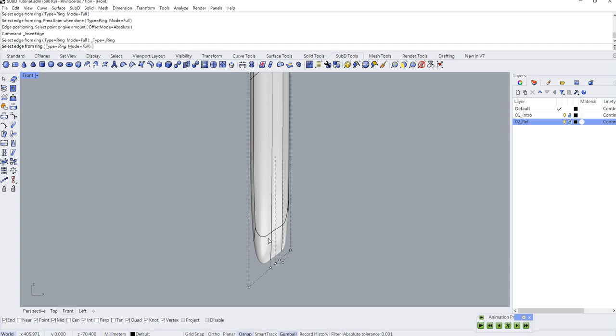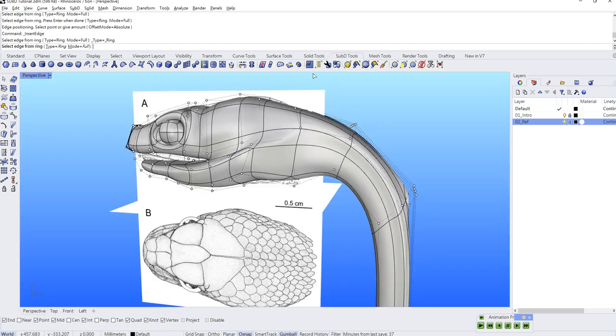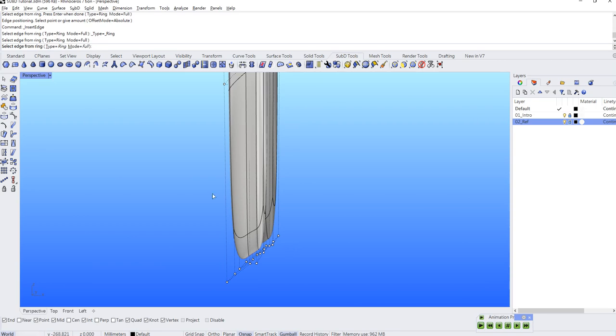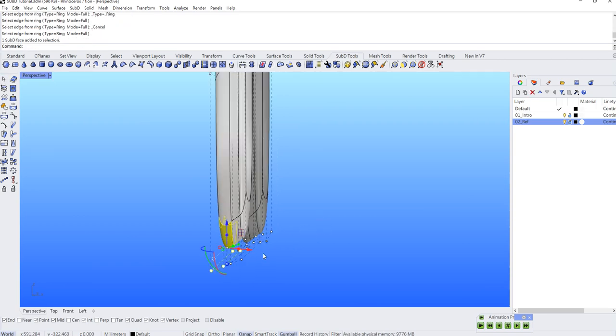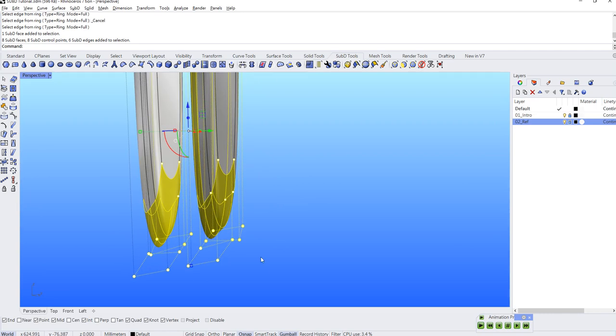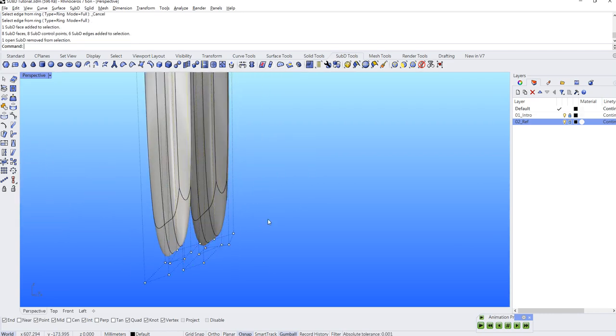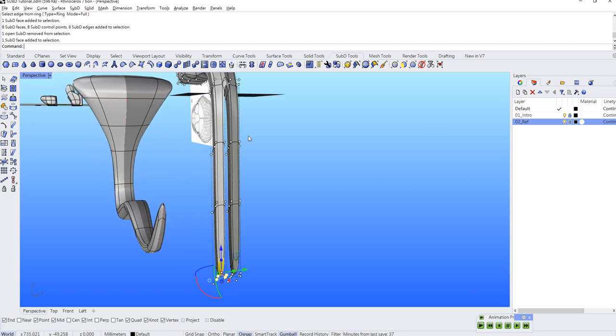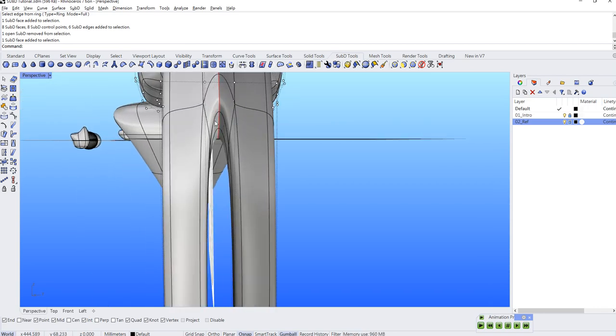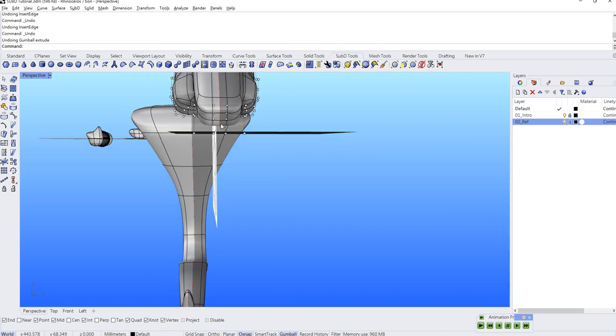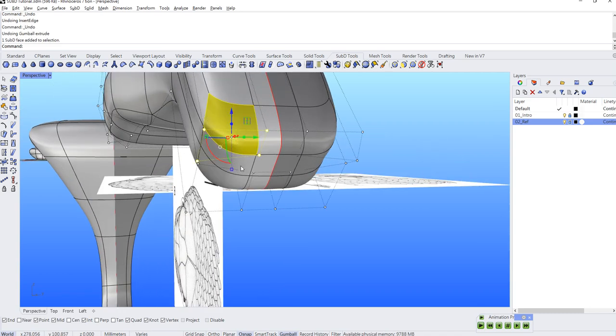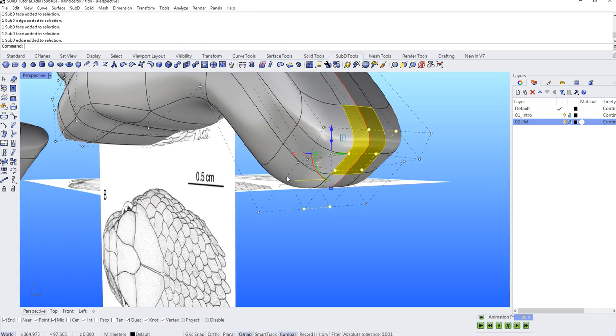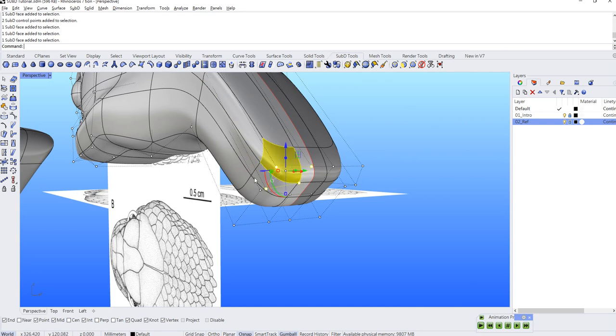For this part, we can select the face again. Go to perspective, hold on your Shift and Control key to select all the faces right here. Make sure you are not selecting other things. But there's something wrong, because when we are going to extrude, I forgot to select the middle. Unfortunately, I have to redo that, but it's okay. I think the most annoying part inside Rhinoceros is that it allows you to select the edge and the vertex at the same time.